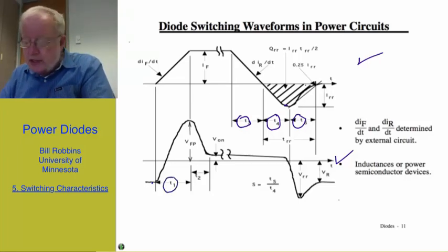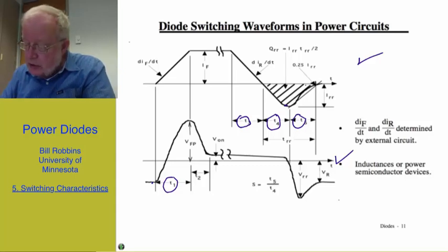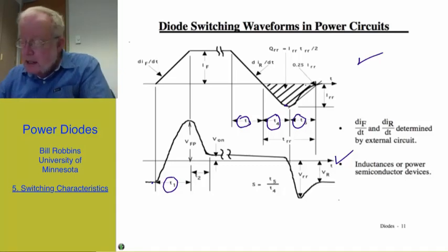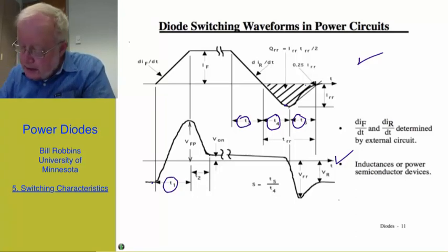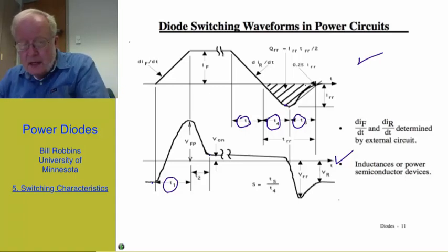So there's a voltage overshoot that occurs in the time t1. When the current reaches its on-state value, that voltage then drops down from the peak forward recovery voltage down to the on-state value in a time t3 that we have, or t2 that we have already talked about. I guess I was talking t1 here, and here is t2. It remains at that on-state value of 2 or 3, possibly 4 volts during the rest of the on-state interval.